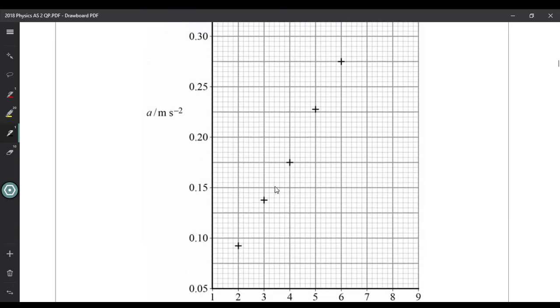Now, when you draw the line, make sure that it's a continual ruled line. And also make sure that your pencil is really sharp, so the line itself is very thin, because the thicker the line, the more uncertainty there is going to be when you're looking at positions of points.